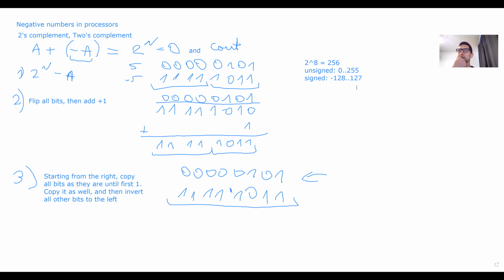So obviously you get less possibilities. And some people get confused: how does the computer know if we're working with signed or unsigned numbers? Actually, the computer doesn't know. It's up to your code to define variables, for example in the C programming language, as signed or unsigned, depending on your application. It just adds bits and that's it. So you have to remember that, for example, if you're working with signed numbers which go from -200 to +800, you cannot use an 8-bit number. You need to use, for example, a 16-bit number. The computer doesn't know it. Okay, so this is how we can convert numbers.